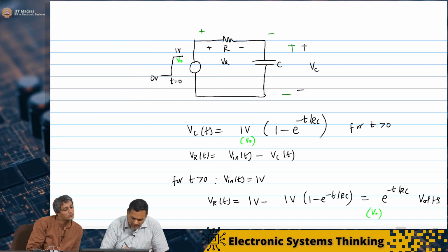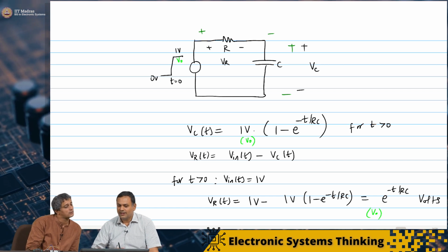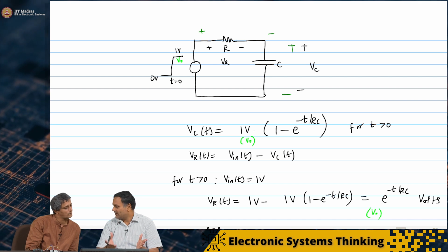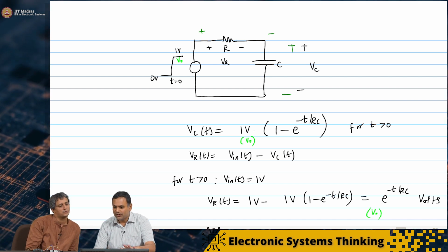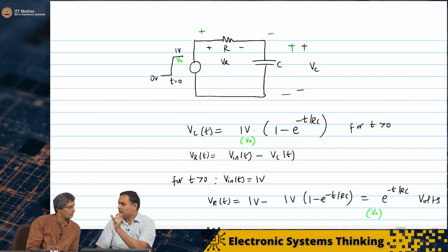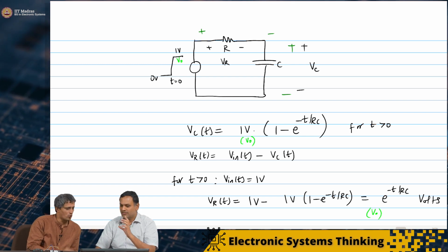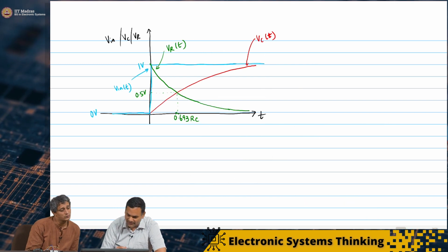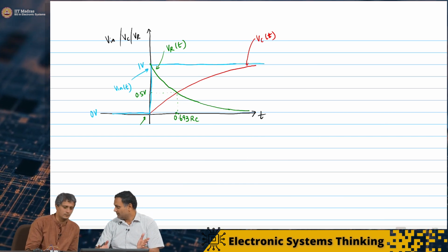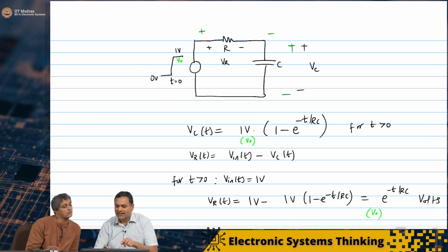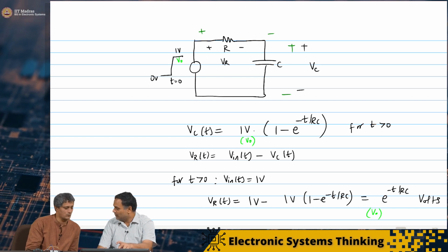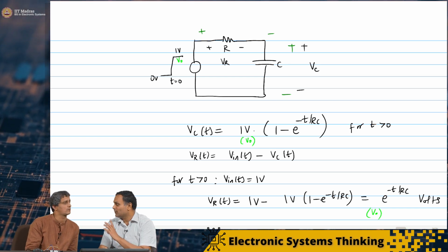Well, a good way to look at this is to look at the voltage across the resistor when the input is 0, at time just before t equal to 0. 0 minus. Yes. So in fact, that would be in this region. You can also plot all voltages. And what you will find is that, of course, the capacitor is assumed to be initially discharged. The input voltage is 0. So by definition, the voltage across the resistor also has to be 0.